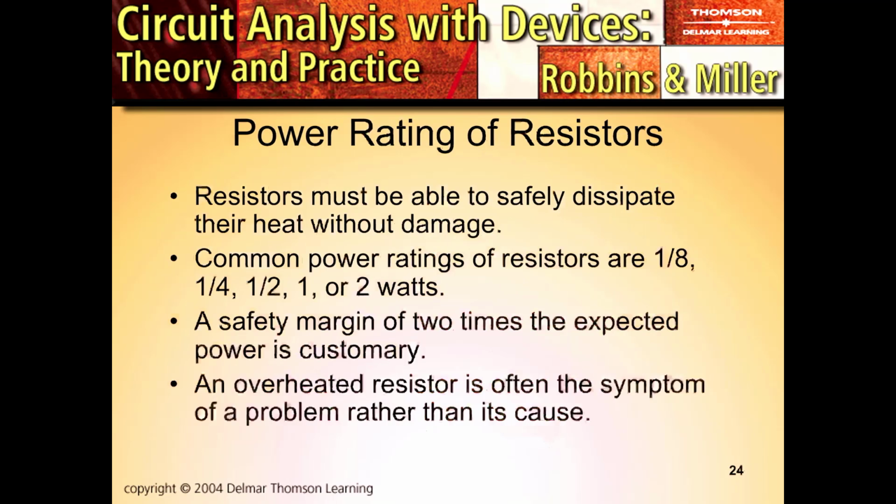So one thing we have to be aware of when we're working with problems that involve power is there's two power values that we could see in a problem or in an example. One of them is the actual power being dissipated by the load, and the other one is its maximum power rating, meaning that it's a rating saying if you exceeded that power, you could damage it.